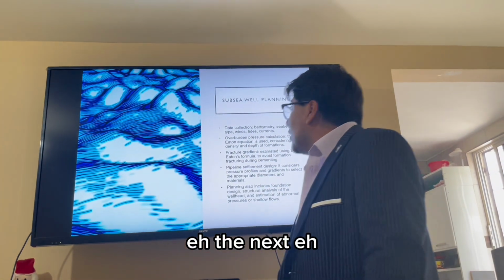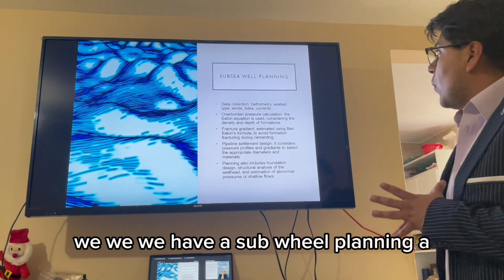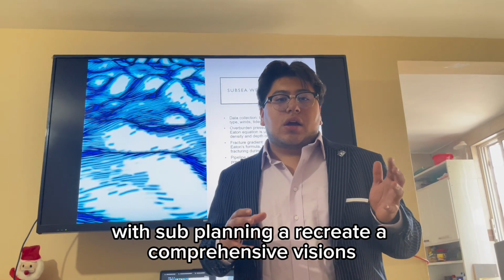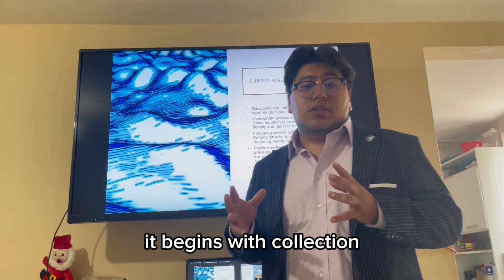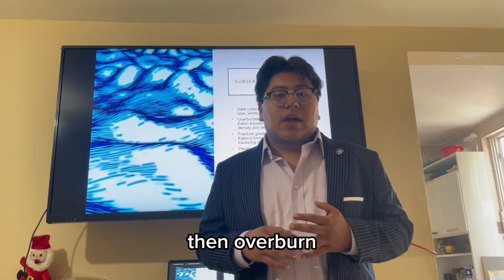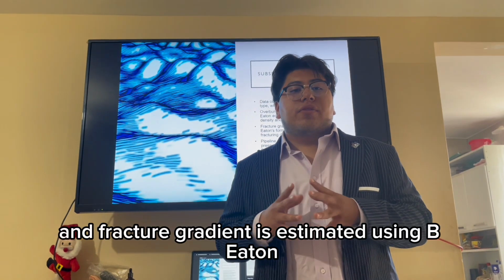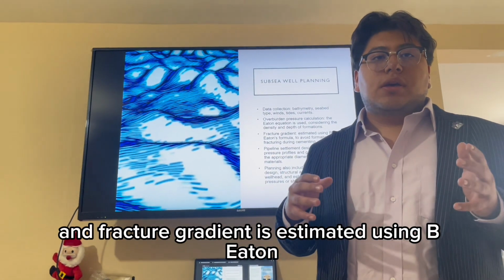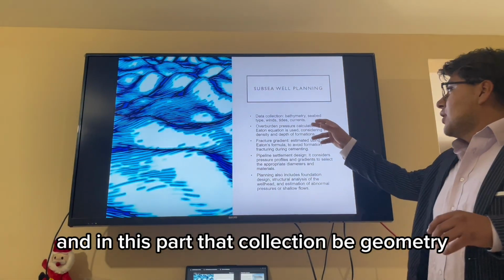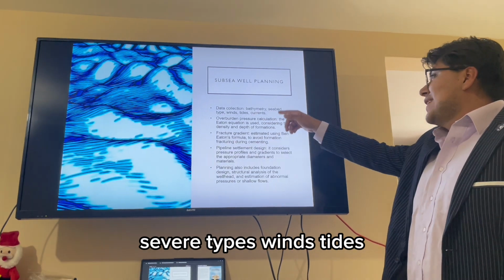The next, we have subsea well planning. With subsea planning, we face complex conditions. It begins with collection of oceanographic and geologic data. Then overburden pressure is calculated using the Eaton equation, and fracture gradient is estimated using Eaton. In this part, the data collection includes bathymetry, sea state, wind, tides, and currents.